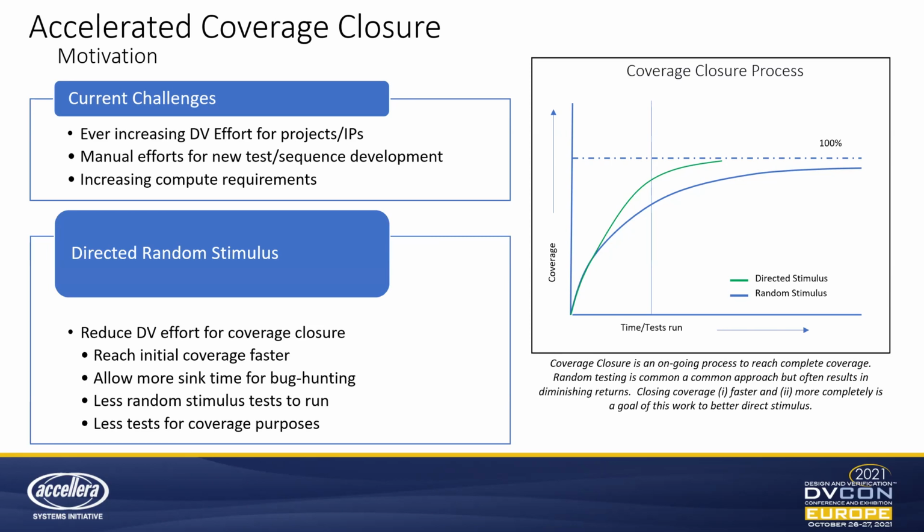This is using the UVM constrained random stimulus generation, directing this as required. So really this is building on top of constrained random testing. Something that we define here is directed random stimulus, and this provides an approach to utilize random or generic test cases and stimulus generation to better target coverage requirements. And this is what we're aiming for in the green line, ideally.